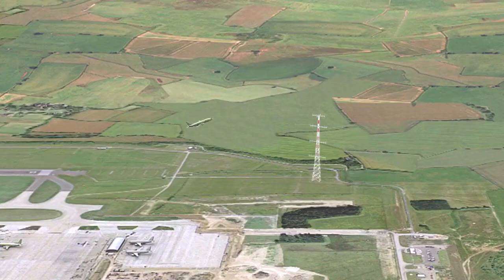One of the last masses to consider is the obstacle limit mass. The obstacle limit mass is the maximum mass, in the event of engine failure, that the aeroplane can be at in order to achieve the minimum clearance over an obstacle in the takeoff flight path. If the mass of the aeroplane were greater than the obstacle limit mass, then there is no guarantee that the aeroplane will clear the obstacle by the minimum clearance level.